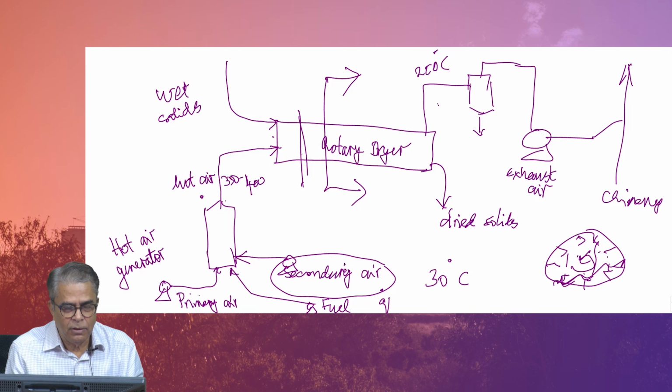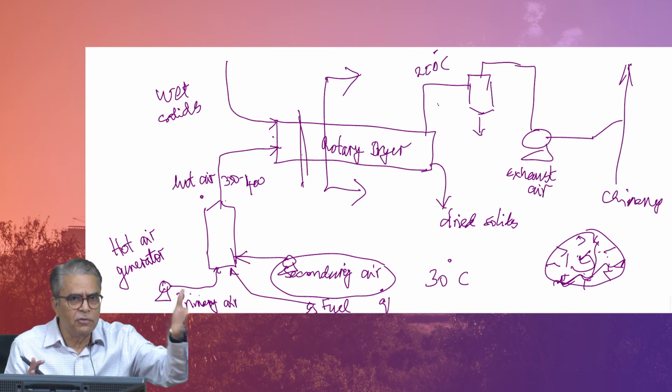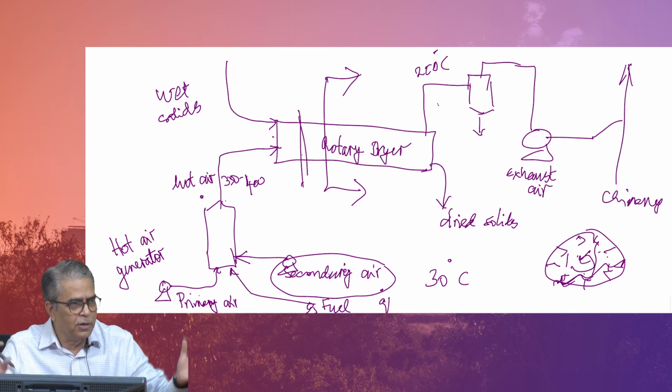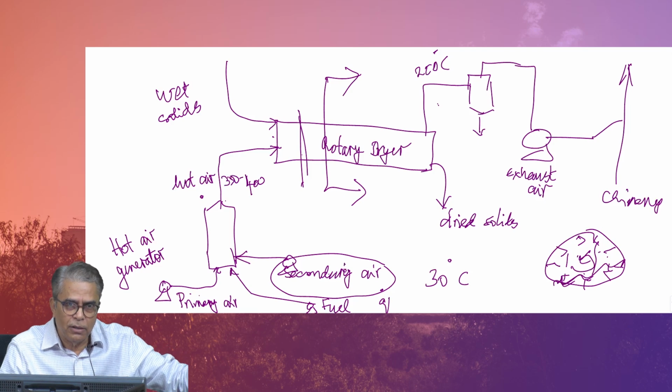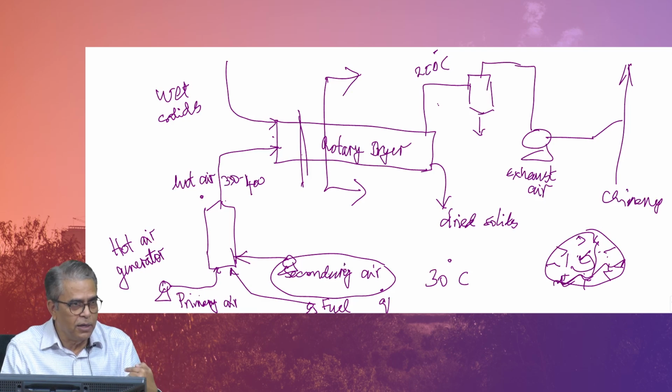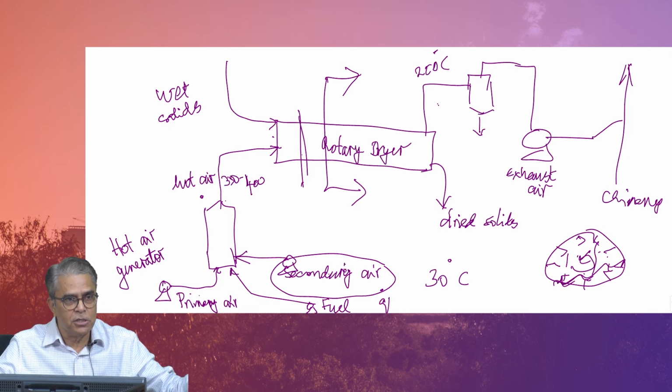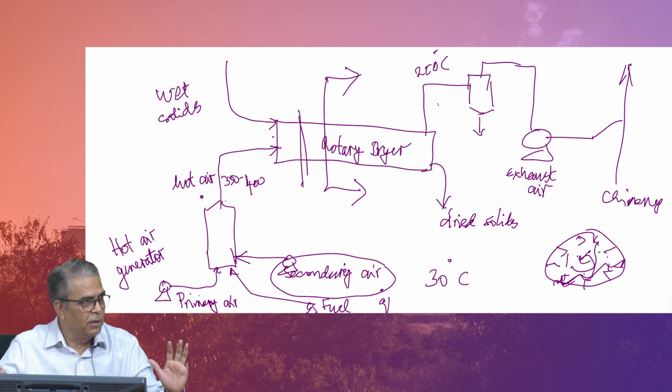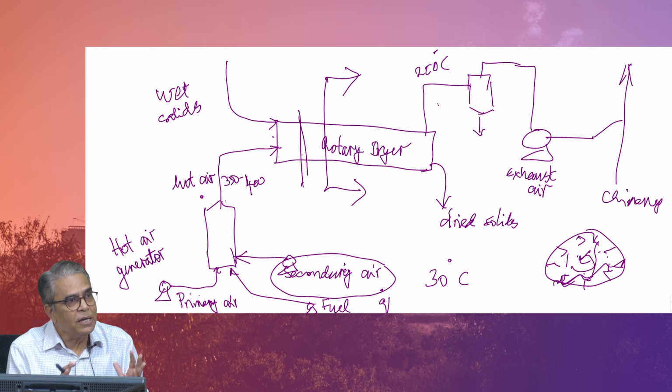What is the meaning of network? There are lots of heat exchangers here, everywhere. Each one is having one stream which exchanges to another stream. So, every heat exchanger will have two streams, one stream transferring heat to the other stream which is picking up the heat. So, if you have n number of heat exchangers, you would theoretically have 2n streams going around. You have some configuration. The question is, is that the right configuration, the optimal configuration? The analysis is heat exchanger network.